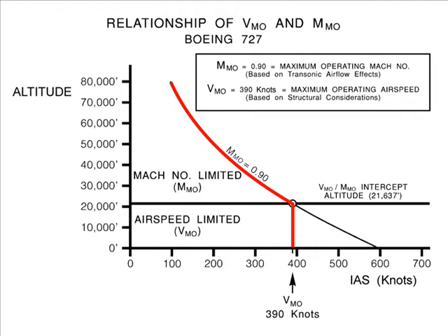During a climb at constant indicated airspeed, true airspeed increases to balance the decrease in density. Mach number is the ratio of the true airspeed to the speed of sound. The increase in true airspeed during a constant indicated airspeed climb, combined with a decrease in the speed of sound as the temperature decreases, means that the Mach number is also increasing with altitude.